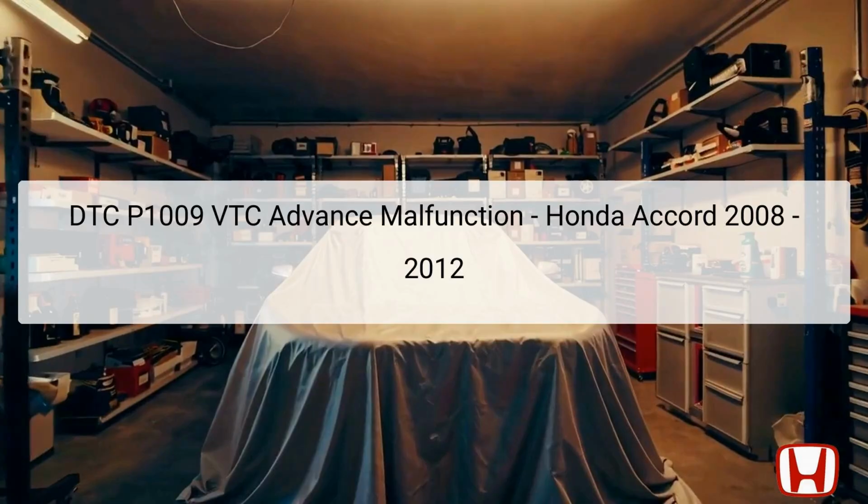The DTC P1009 indicates a VTC, Variable Timing Control Advanced Malfunction, common in the Honda Accord models from 2008 to 2012. VTC is a system that optimizes engine timing for better performance and efficiency by adjusting the timing of the intake camshaft. The affected components primarily include the VTC actuator, VTC oil control solenoid valve, and the VTC strainer.